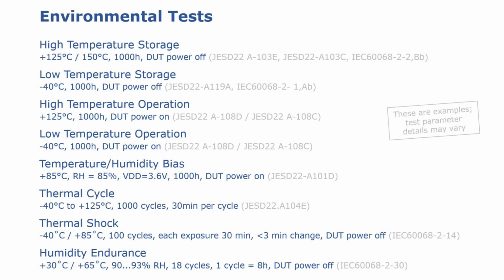There are also environmental combination tests, in which microphones are subjected to a series of tests. The tests can include various combinations of, for example, temperature cycle tests, drop tests, and a humidity endurance test. After the exposure to environmental conditions, the microphones are typically allowed a recovery period, which can be, for example, 2 hours.